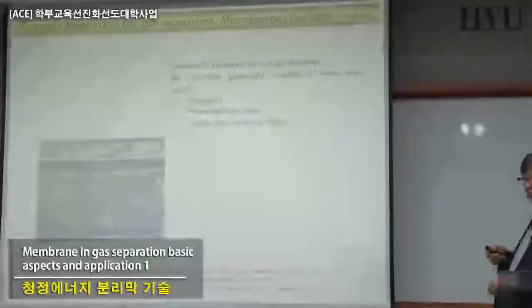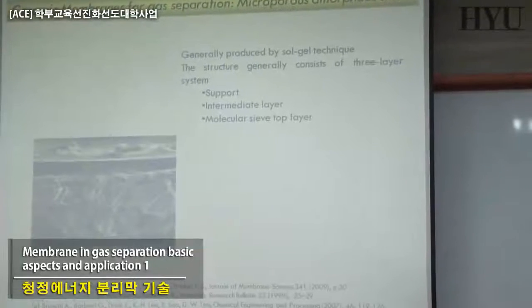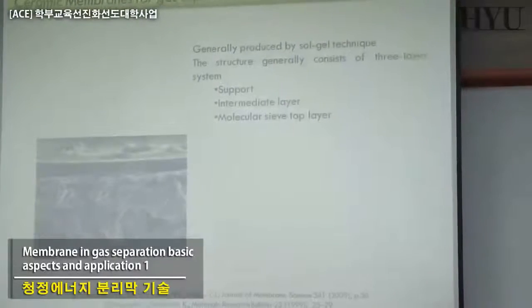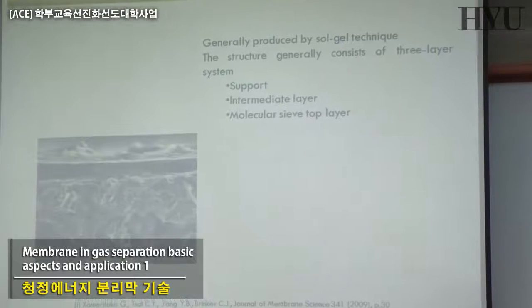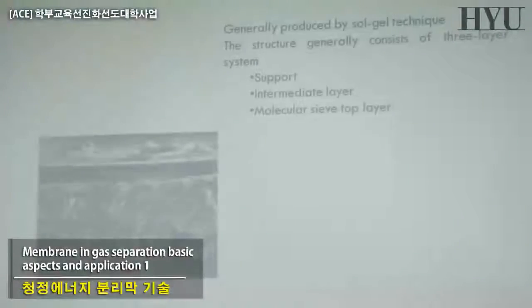and we saw the equations that control the selectivity in this case, which is nothing more than Graham's law, in which the smaller molecules move faster than the bigger molecules, and the equation gives you a ratio in the selectivity, in the permeability, through the square root of the inverse of the molecular weight of the penetrants, basically.